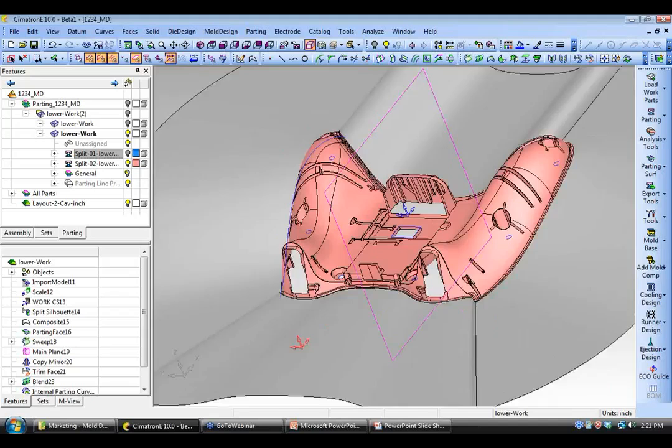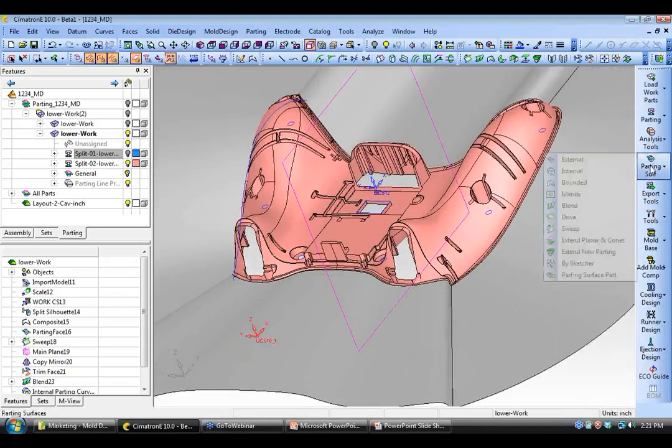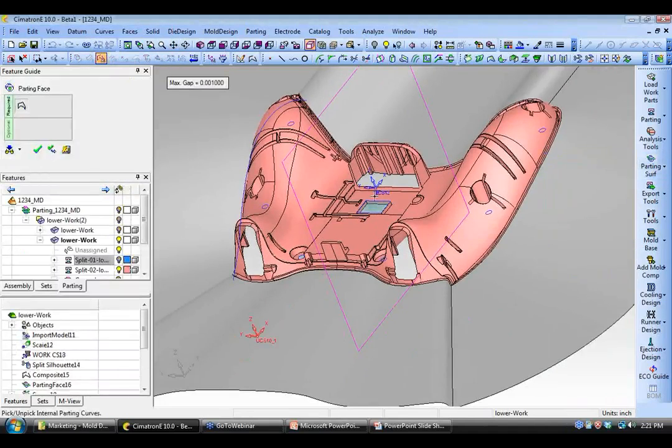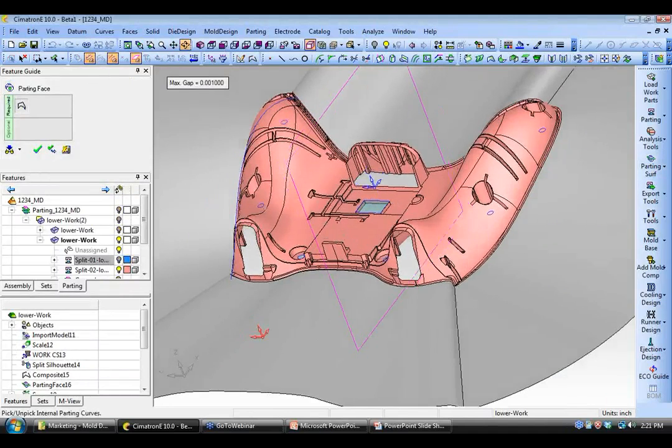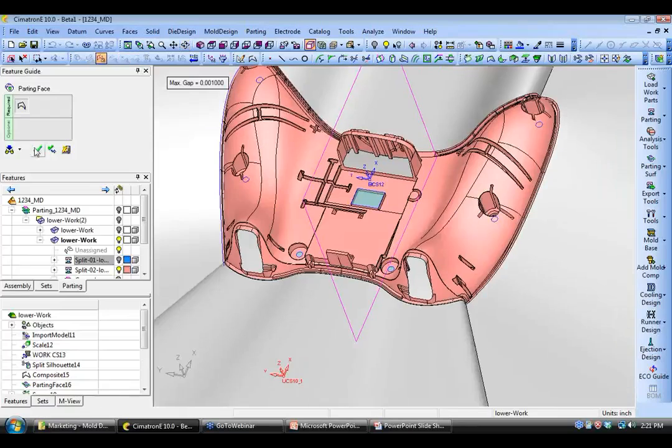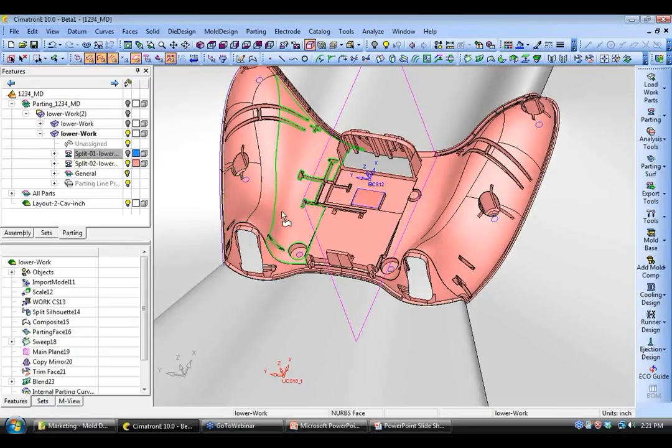Now we saw how the external surface worked. So here we're going to use the internal surface command. It seals off any of the flat or the contoured areas that we ask it to do, really in one click. And this can be a huge time saver for parts that have a lot of internal islands. Now, more difficult areas need something else.